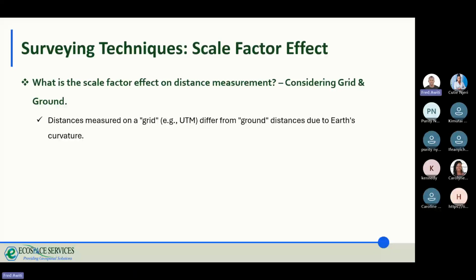So that is what we call projection. You are taking it from a 3D representation to a 2D representation. In any measurement, as long as you start doing transformation, you're introducing errors. When the laser is traveling from one point to another, there's refraction. The light has to be bounced back. When it is bouncing back, the time taken is what is being used to measure the distance.